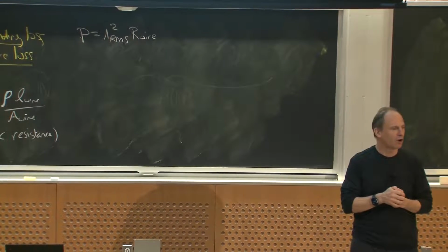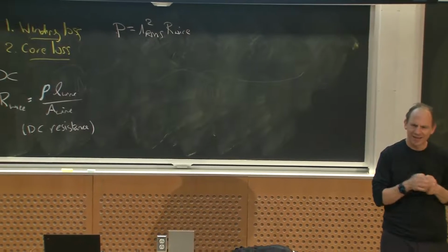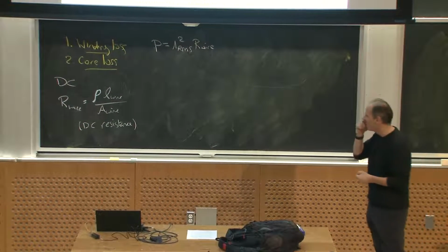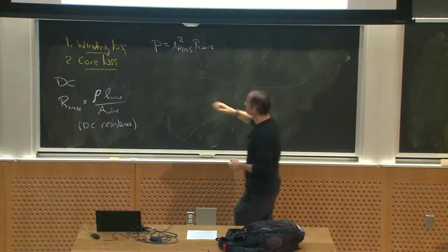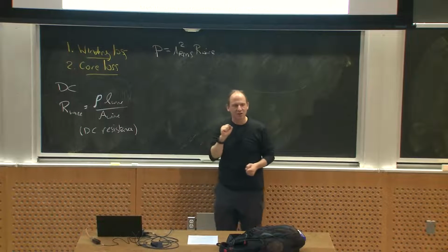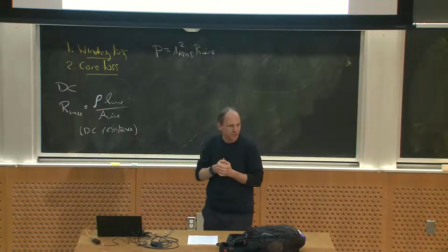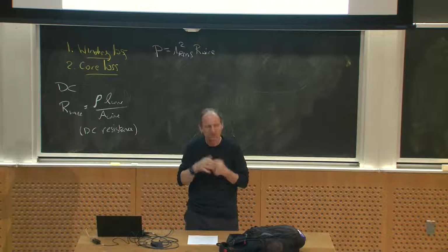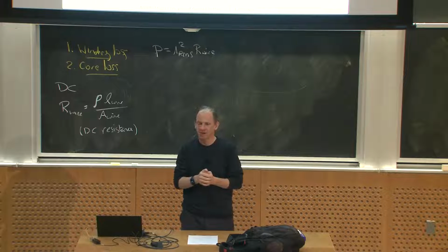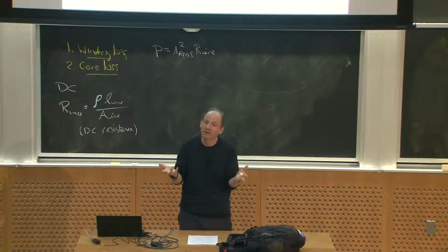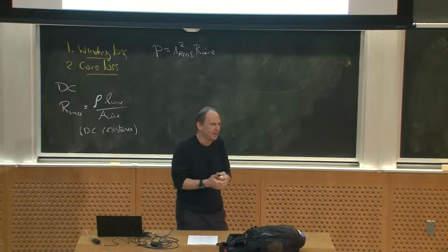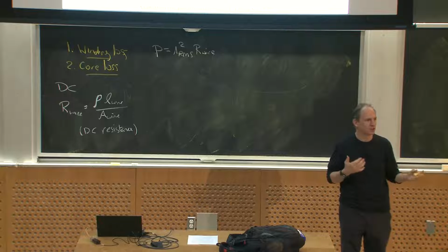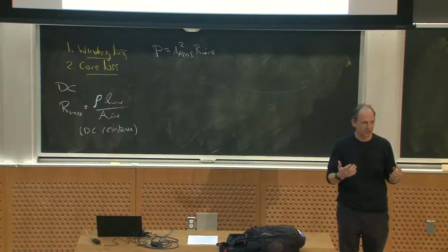So something that often comes up when you're doing this is exactly how much current I can put through that piece of wire. What's the allowable RMS current that my wire can carry? That's an interesting question because there's not a single answer to it. It's usually dictated by how hot things are going to get, and that in turn makes it dependent on heat transfer. Now, we haven't really talked about thermal models and heat transfer yet, and we will.